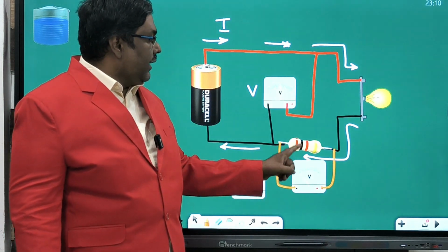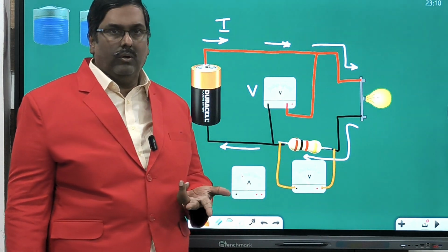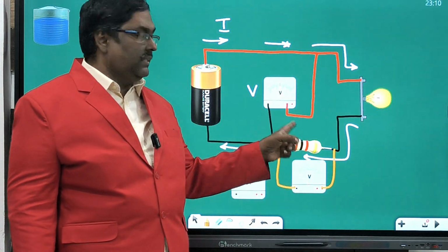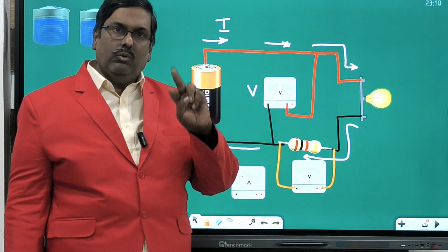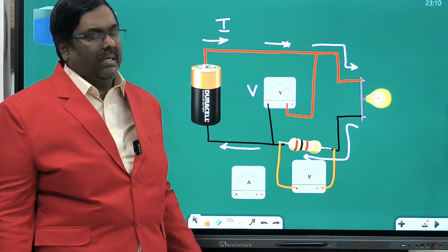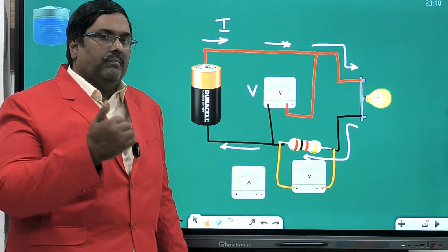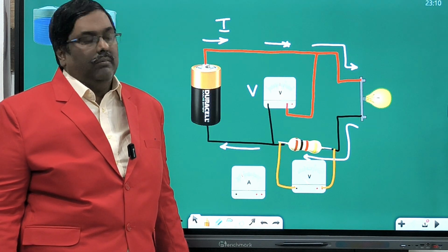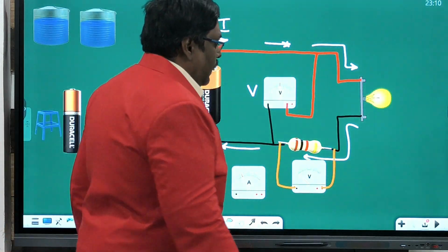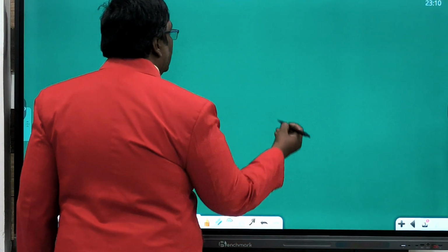Understand? Now, okay, now I put the resistance. Now I measure the volt. Now what things did you get? We got volt and resistance, you know how much you put. We have two values. With the two values, how to find the amps? Because it is showing the voltage only. Now we have to convert the voltage into amps. For that, Ohm's law. This is a very, very important law. Ohm's law.